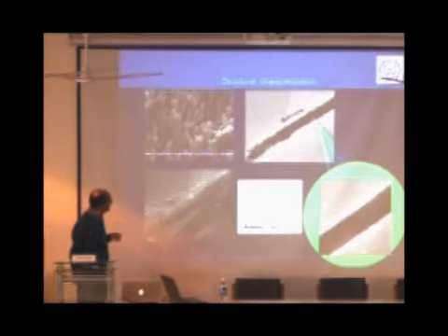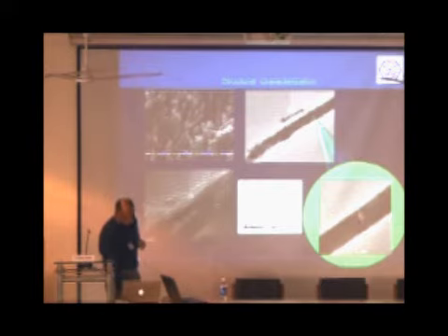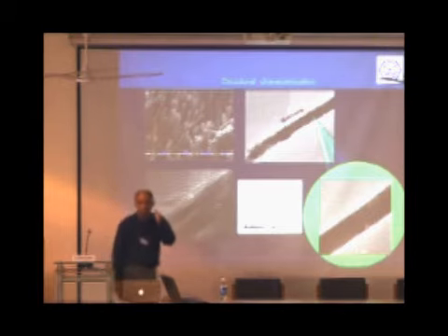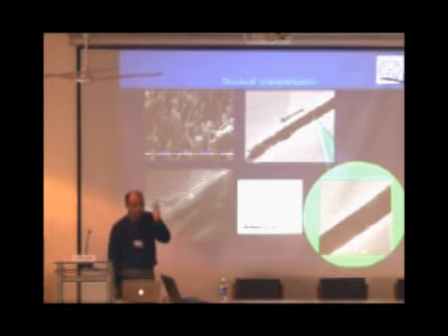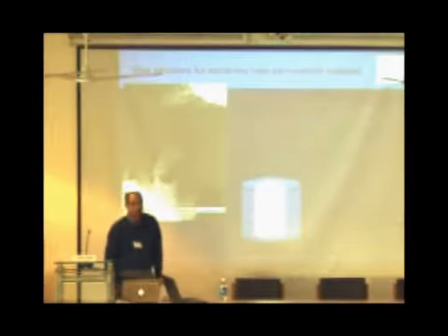These are cobalt palladium nanowires with really sharp interfaces. If you zoom in here, you can actually see the palladium, which is the dark area, starting from about here till about here, and then the interface is extremely sharp. What that means is the cobalt and the palladium, the magnetic and the non-magnetic interface, is extremely sharp, and it will not scatter spins. Rather, if you have a diffuse interface, you get what is called spin flip scattering at the interface, and that destroys the magnetic transport in such nanowires.